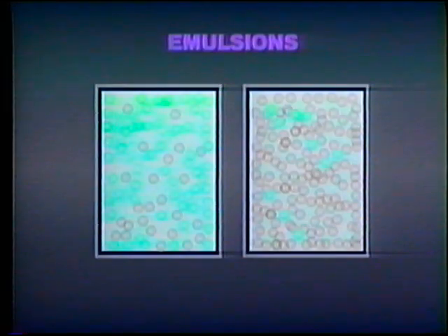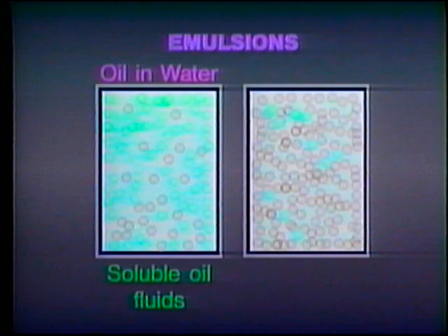A soluble oil fluid usually contains 90% water. Since water is a poor lubricant at the high pressures common in modern hydraulic systems, soluble oil fluids aren't as widely used as they once were. However, they are inexpensive, so you'll still see them used where the decision has been made to accept reduced component life in favor of an inexpensive fire-resistant fluid.